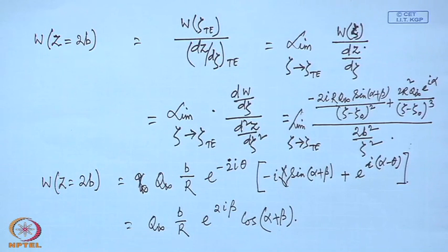So, as we discussed at the beginning, for a Zhukovsky airfoil which has a cusp trailing edge, the velocity at the trailing edge is not 0, but is finite. You can see this is the finite value.